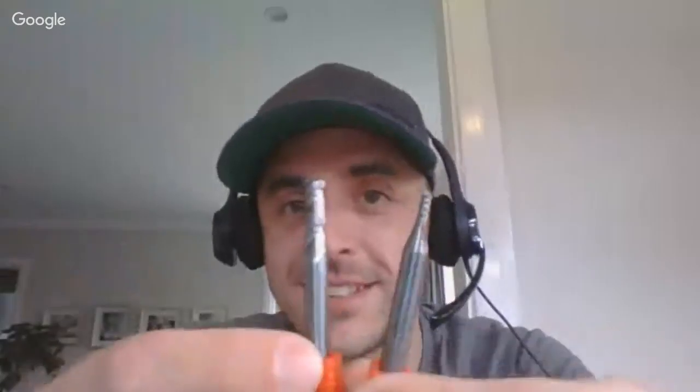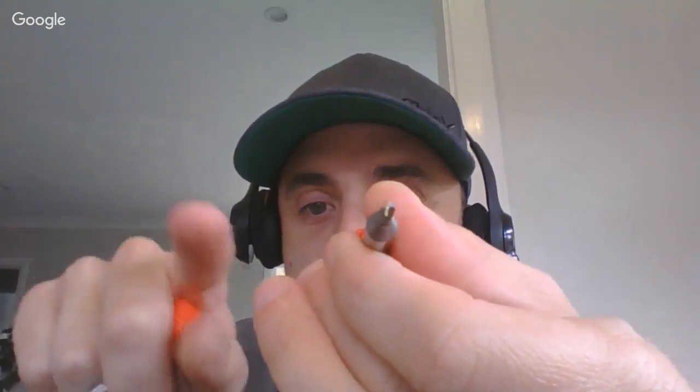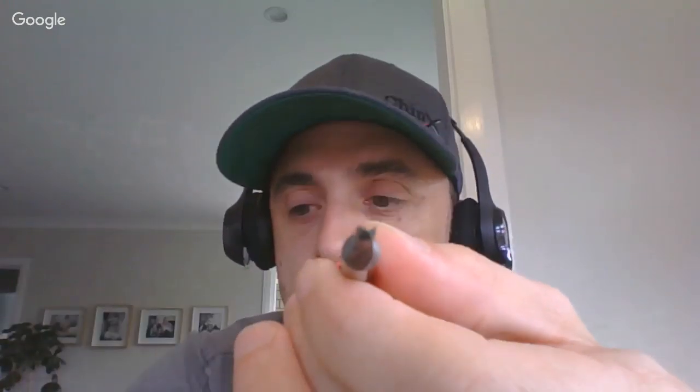Really, wouldn't it, Gavin? That's a great question, and the reason I like it is that it raises a really important point. We were talking about surface speed before. Just to recap, that surface speed is how fast that cutting edge is traveling through the material. Obviously, the smaller the diameter, the smaller the circumference of the cutting path. If you take it to the extreme and go to a pretty close to sharp point, you have almost no circumference, so it doesn't really matter how fast you spin it.